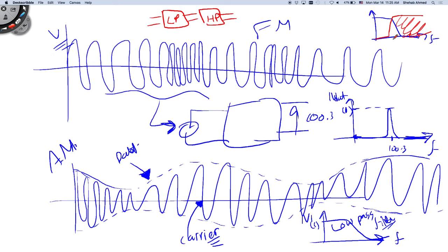And then I pass the same signal through a high pass filter. I eliminated everything here. What am I going to be left with? Everything in this range of frequency, right? So that's why we don't study notch filters specifically, but it's basically a cascading effect of low pass and high pass. So everybody's okay with this idea of low pass filtering, high pass filtering. So now we have to figure out circuits to do this, to fit this criteria, right?